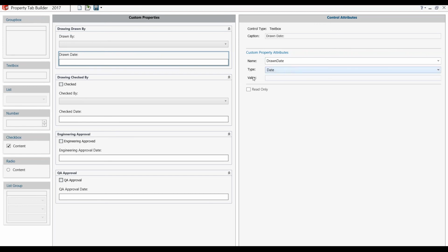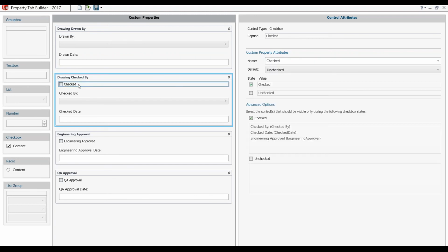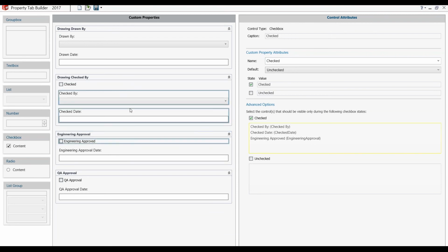and I'm going to hit the Save button. So I've saved that sheet format, but technically this drawing document isn't referencing that sheet format because when it got a format, that format didn't exist. So I'm going to go to my sheet properties, and you can do that by right-clicking on the sheet and hitting the Properties button. And this is everything that is stored at the sheet level.